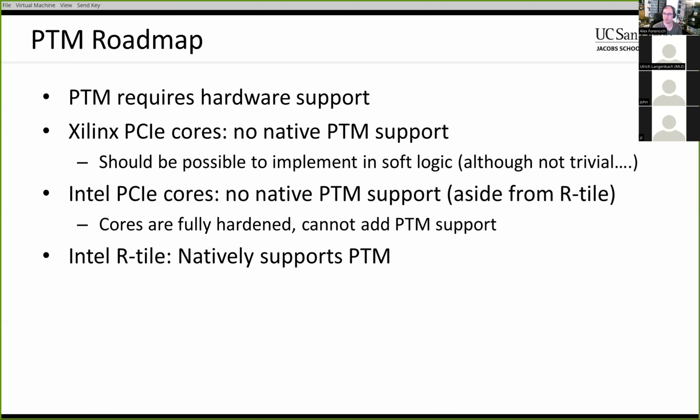For Intel cores, it's kind of a similar situation where nothing except for the latest Agilex I-series devices with the R tile supports PTM. But unfortunately, on the Intel devices, everything's all totally hardened. You can't access anything between the serializers and the PCIe hard IP core. So it's not going to be possible to add PTM support on most of those. But the R tile natively supports PTM.